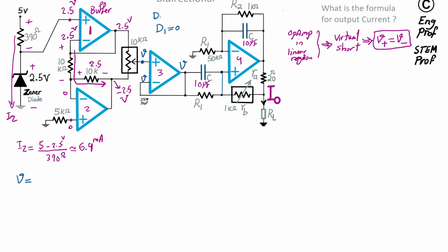When the digital code word for this potentiometer is 255, then this pointer is connected to here, which means the highest voltage, and therefore V is almost 2.5 volt. And this happens linearly depending on the value of the code word D that moves between 0 and 255.